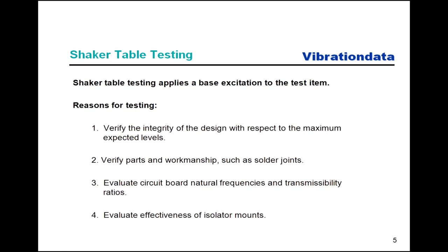So there may be a lot of 100 different pyrotechnic devices, and then some 5 or 10 of those will be subjected to qualification testing, or what's actually called an equivalent lot acceptance test, even though it's probably at qualification test levels. Those units will be tested and then detonated to make sure that they can still perform their function after vibration. And at that point we'll say, well, the other 90 or so units are good to go based on the fact that we had 10 units that passed lot acceptance testing.